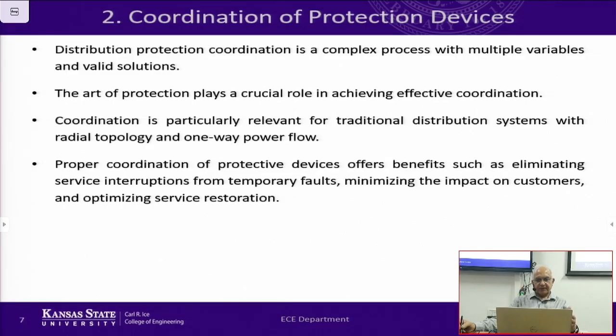Anyway, this is again something that I already talked about, which is the aspect of coordination. That is, we need to select devices in such a way that they coordinate for all possible ranges of fault currents. And one thing you should keep in mind is that the selection of devices is not an absolute thing.